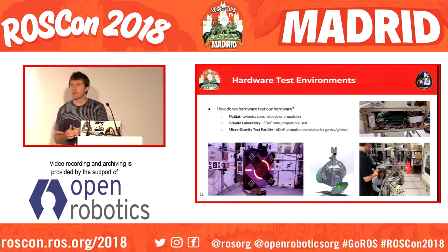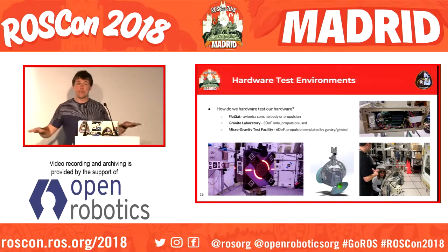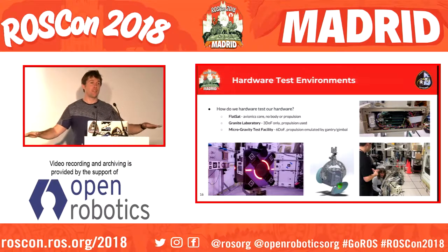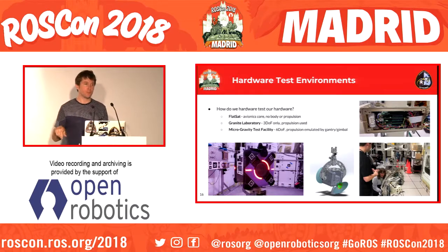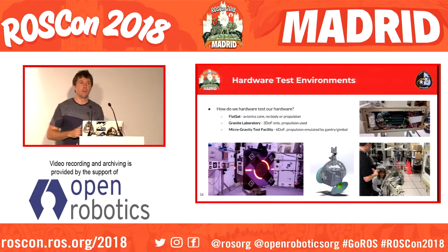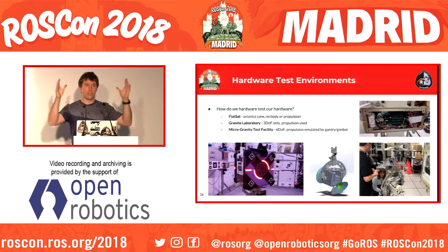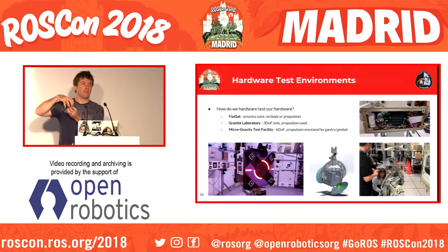Some of you might have that if you're part of a research group that does space robotics, but it's a really, really flat granite table mounted orthogonally to gravity. Essentially you have air pucks that blow out CO2, and then you float on a pocket of air. So you have 3 degrees of freedom, 2 translation and 1 rotation. We're also in the process of building a microgravity test facility, which is like a long room with a gantry, sort of like a room-sized 3D printer, with a gimbal at the end, and that can allow us to move with 6 degrees of freedom.